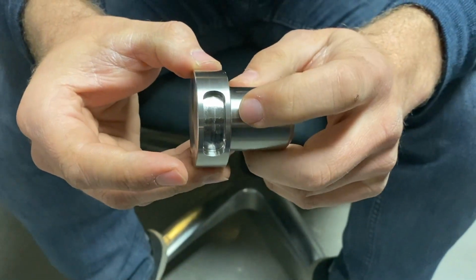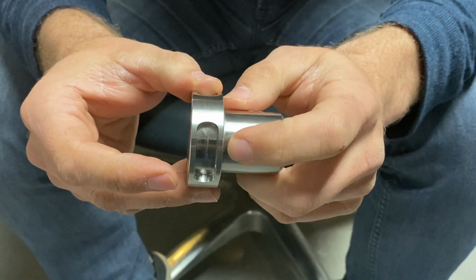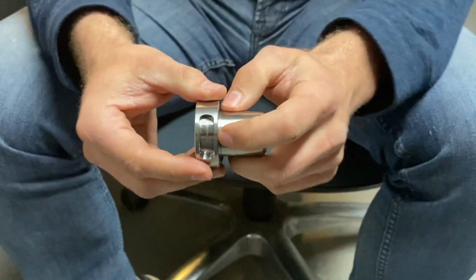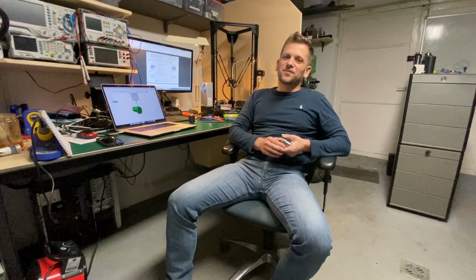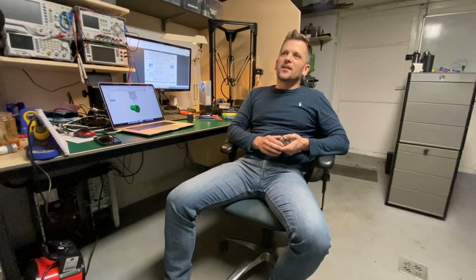This time my code was fine. I mean, my UI was fine, but this happened because of a bug in Fusion. I had two operations, a 2D adaptive and a 2D contour, a wrapped 2D adaptive, and the Fusion post-processor for LinuxCNC has a bug. When it finishes the first operation, it has a condition that says if it's a rotary axis, cancel tool length compensation.